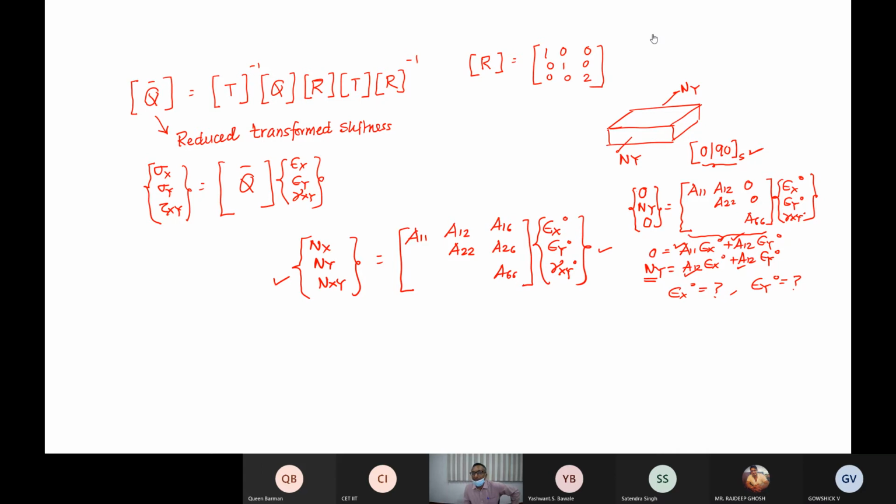Yeah, so what I was telling is this, you're right, we don't load a single lamina. Even though we say that E1 is the longitudinal Young's modulus of a unidirectional lamina, when you conduct the test in UTM, just go back and see the slides. There are certain standards we follow. Maybe we take 6 to 8 0-degree plies having certain length and certain width. If I remember correctly, the width is around 1 inch, like 25 mm, and the length was around 229 mm. And there is a fixture, like we put some tab to grip it well, okay?